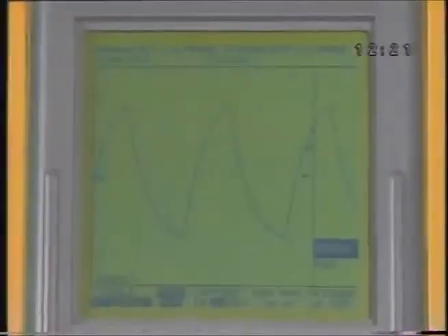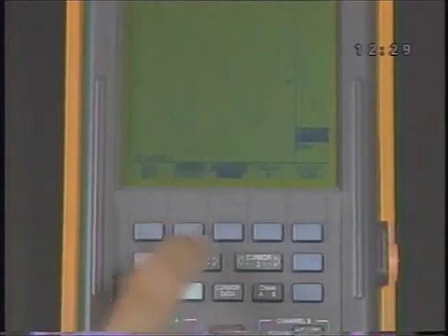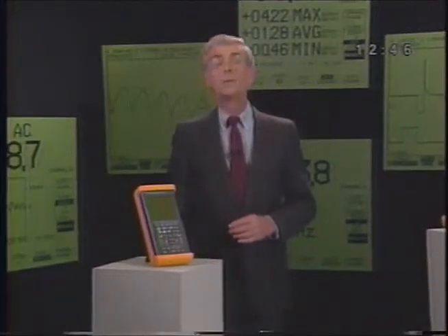You'll also use the simulator included with Scopemeter to produce another type of AC waveform, a sawtooth waveform. And you'll learn how trigger level and slope affect how you view a waveform. Finally, you'll learn how to read and diagnose the waveform typically produced by automotive components that generate AC signals. Make sure you watch this section all the way through before trying it on your own. You'll be told when to turn the tape off and go to the signal generator exercise in your workbook.